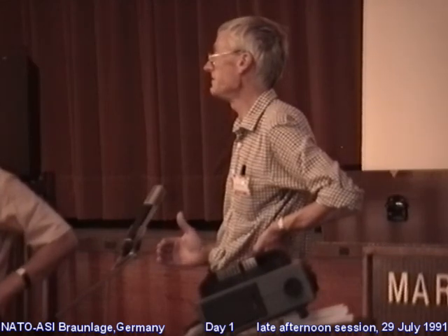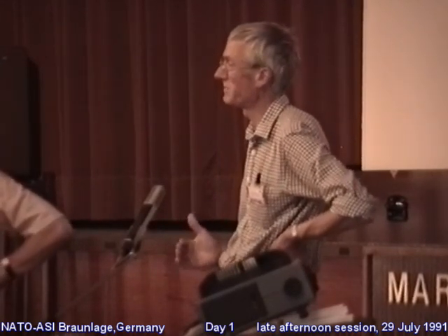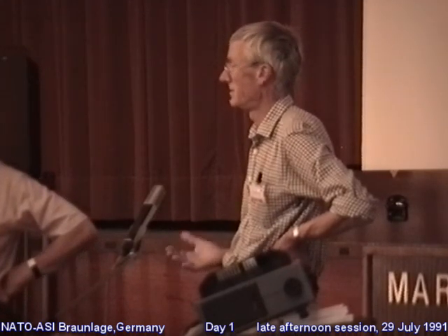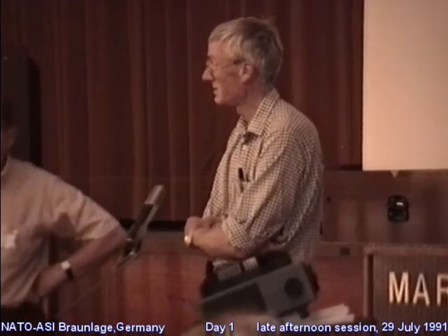I mean, you can get into trouble if you start using multi-asperity arguments because you've got to make sure that the whole is consistent. But at first sight, I would have thought that you have a case where, for reasons of multi-asperity contact, the contact area is proportional to the load. Then this effect that I mentioned this afternoon could still take place, even if the shear stress were a truly constant quantity and hence had zero pressure dependence. I may be wrong, but that's what I would say.